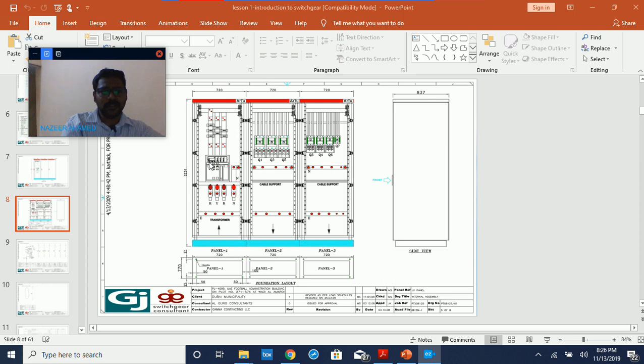And next we checked the trip unit. We have electronic trip units here: LI, LSI, LSIG, with the 3 variants PR121, 122 and 123. PR121 is purely static type, which will have dip switches to set the parameters. Overload setting can be set between 40% to 100% of the rated current of the breaker, and short circuit values can be set between 1 to 10 times of rated current with a minimum time delay like 0.1, 0.2, 0.3 seconds. That is the S version.